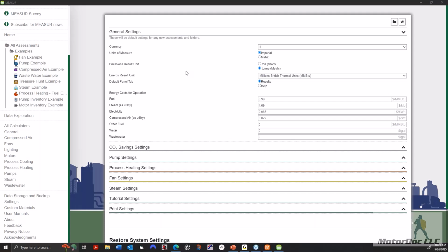You are talking about 10 to 15% increase in the potential losses of a machine that's not aligned at all, meaning not connected to anything. But as you go to a standard alignment or just meeting what people put out there, I believe it's an increase in friction and windage losses by about 60%, or roughly 2% reduction in efficiency on the motor. So the costs do go up and it reduces the life of the machine. So we do know that part.